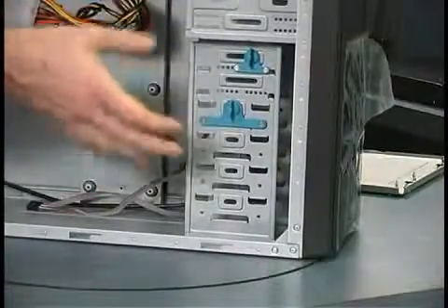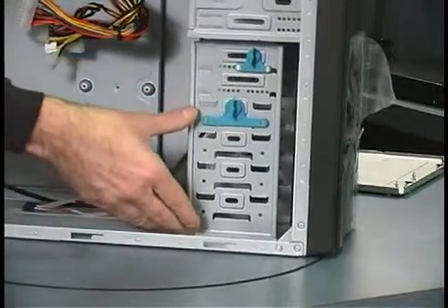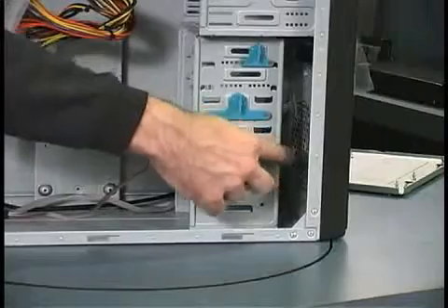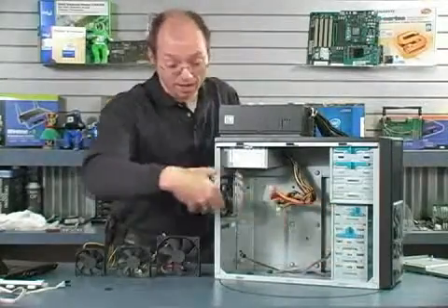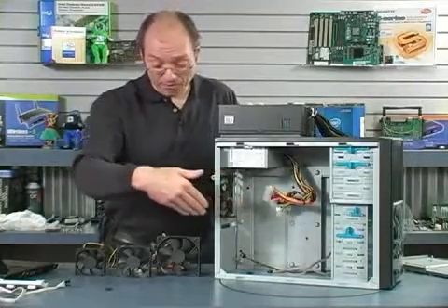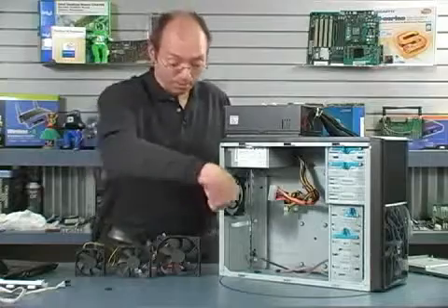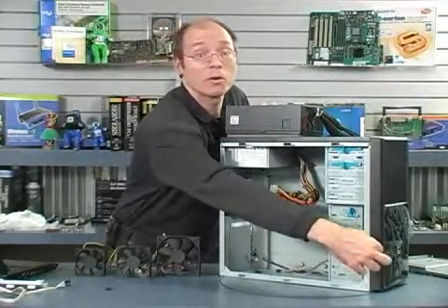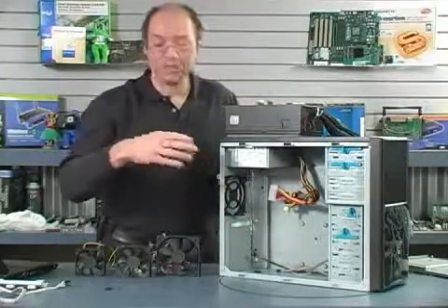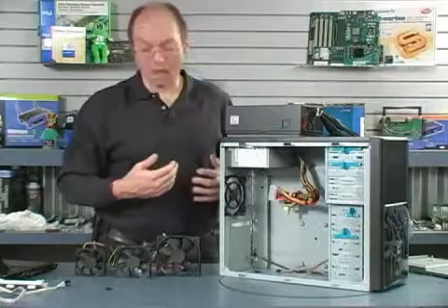Generally, if I'm putting 4 or more hard drives in the front of a case like this, I'll want to add the optional front cooling fan. What that'll do is pull more air in across the drives. So the fan on the back will be mounted so that it blows air out the back, but the fan on the front will be mounted so it blows air in. The key is to make sure you have a balance here. You need more air going out than in.